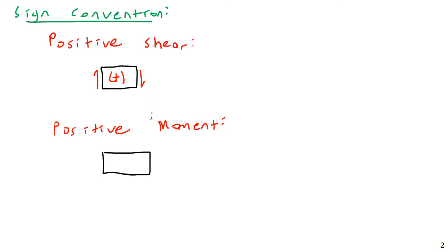What if you have a positive arrow on the right and the left? That's impossible. Even a point load wouldn't matter here, because what I'm drawing is, if you remember from calculus, a differential element, a small dx. Point loads aren't going to occur across a differential element. For an element that small, the force on the left is equal to the force on the right. This thing has to be in equilibrium.